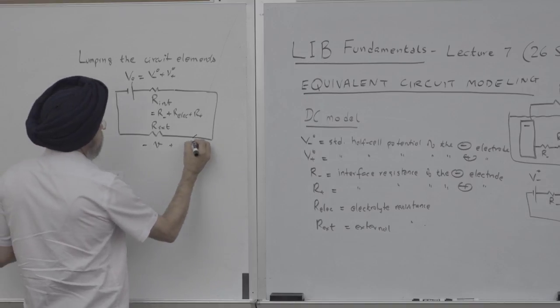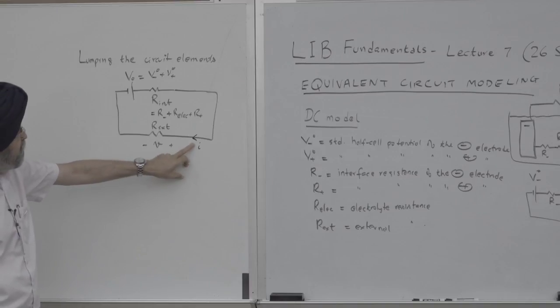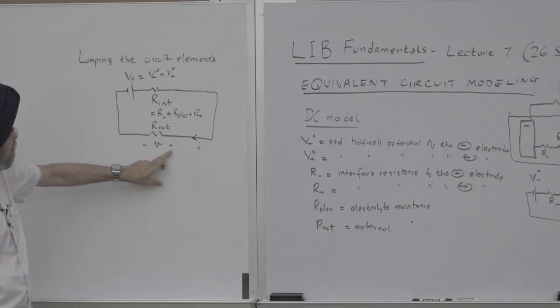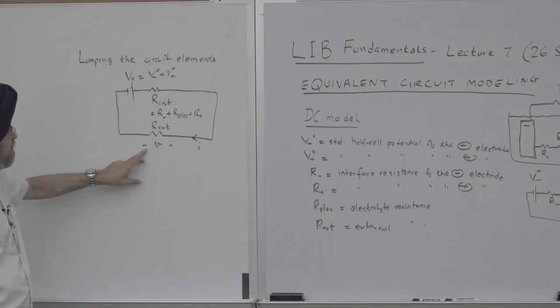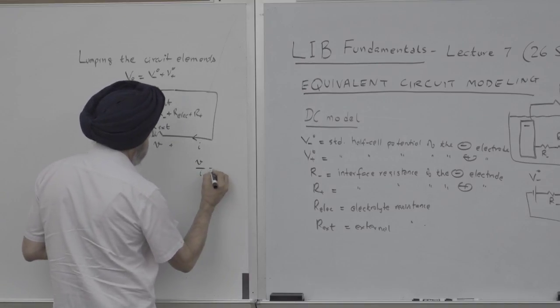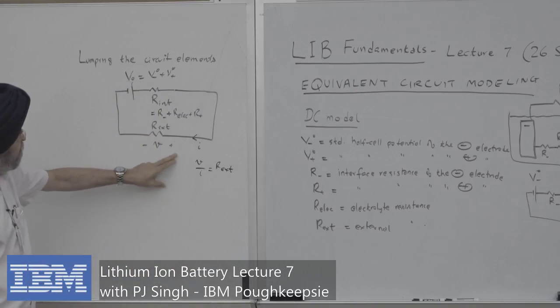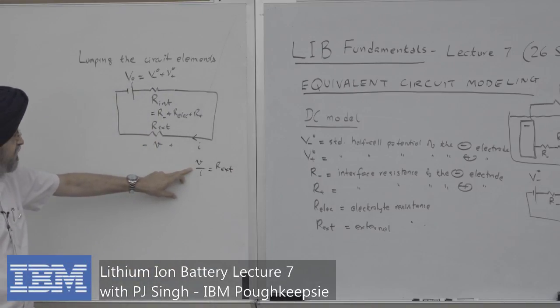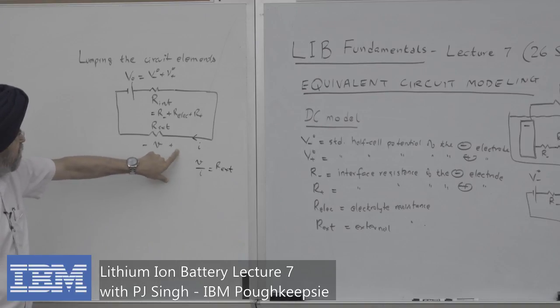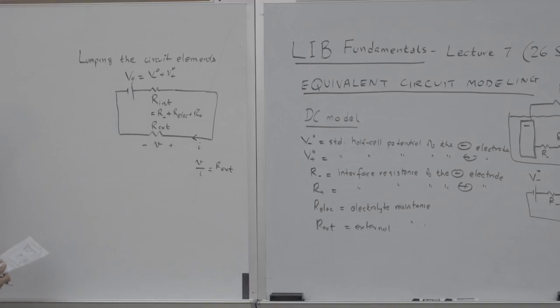So in electrical engineering, it's important to draw the current direction, and then by Ohm's law, we have to say this is positive and this is negative. We can't say negative positive because Ohm's law says that V over I is R, is resistance. So if we were to reverse this, then we've got to put a negative sign. So as a rule, this is how we draw resistors and their polarity.